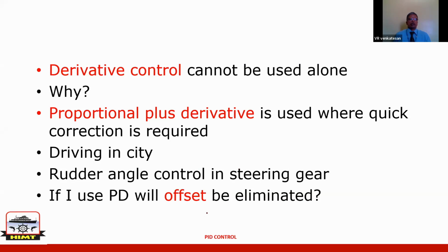So this is for the autopilot control, where you are maintaining the course of the vessel, PID. Okay, so this part we already discussed. If I use PD, will offset be eliminated? Offset cannot be eliminated. Integral is required.